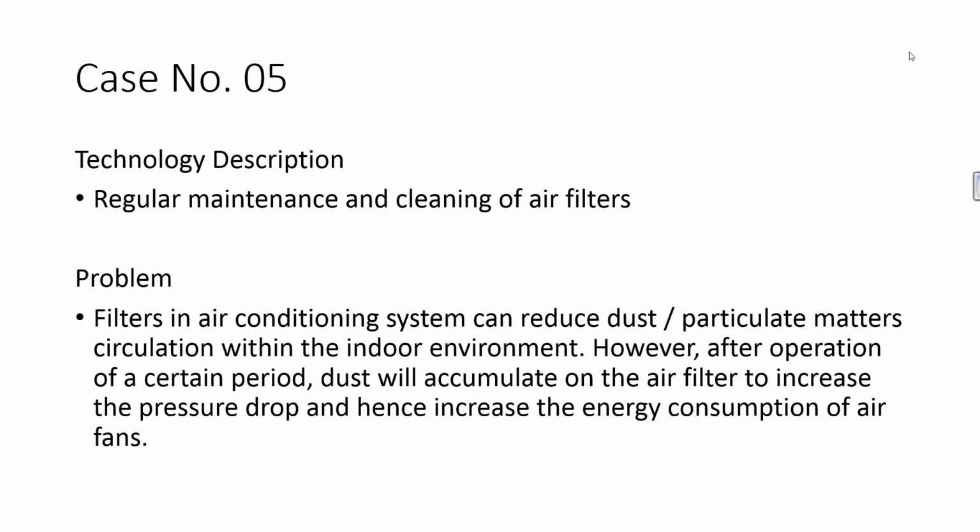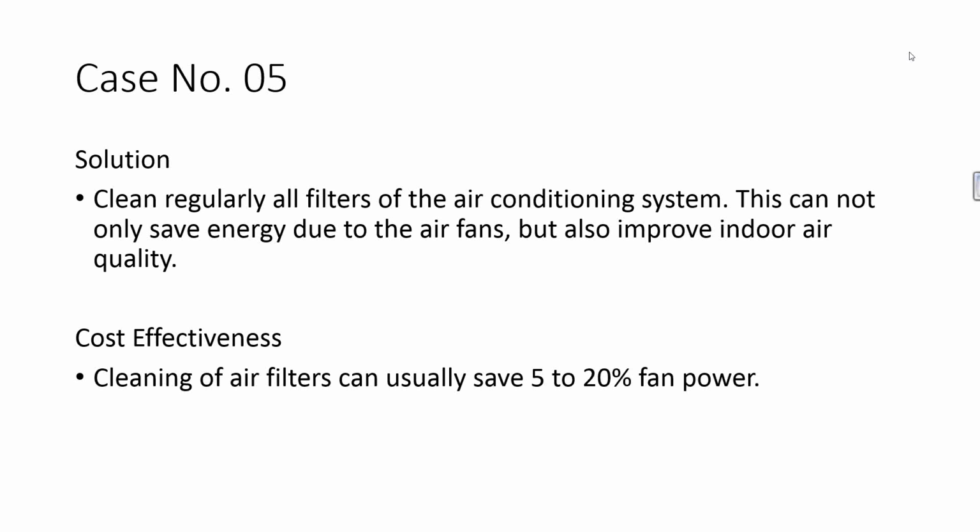The solution for this: clean regularly all filters of the air conditioning system, which can not only save energy due to the air fans, but also improve indoor air quality. The cost effectiveness: cleaning of air filters can usually save 5 to 20% fan power.